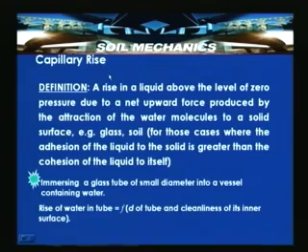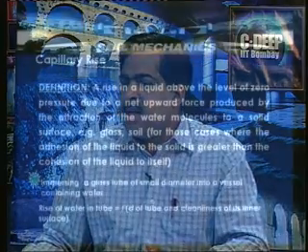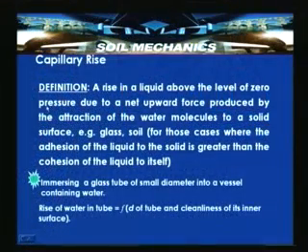Okay. In previous slides we have defined and introduced capillary rise phenomena. Now, let us look into the theory behind this capillary rise phenomena and how it can affect the effective stress. Here is the definition: a rise in a liquid above the level of 0 pressure, that is, at the free water surface the groundwater table is at 0 pressure, due to a net upward force produced by the attraction of the water molecules to a solid surface, that is glass and soil.